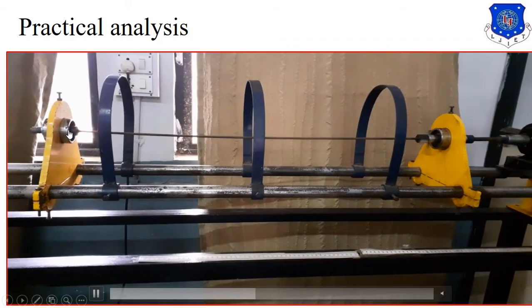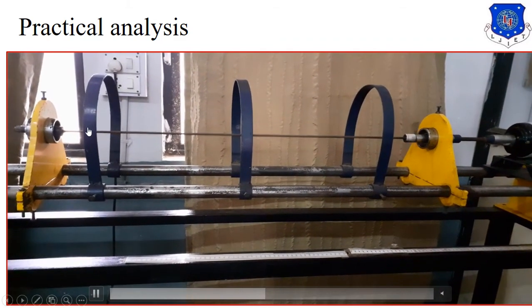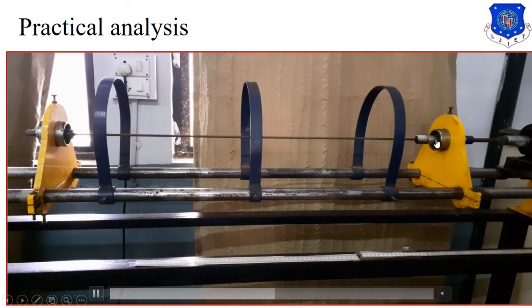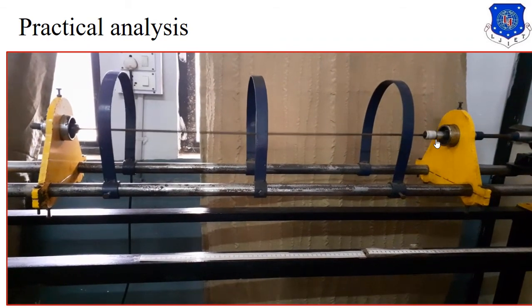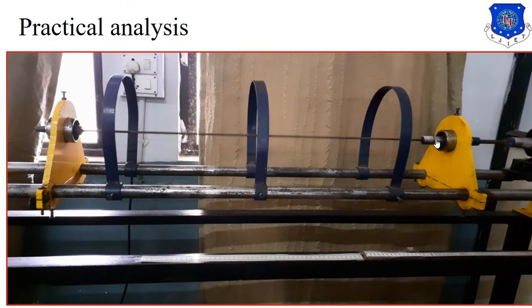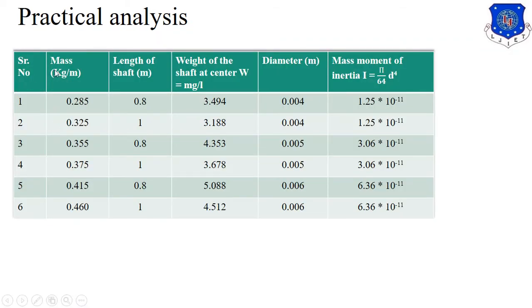First of all, we have to fix both of these bearings. Then we have to fix the shaft at the bearings, and then we have to give it the maximum speed, and then we need to decrease it. By decreasing that speed we can measure the rotations of this shaft. Here we have taken 6 experiments, and